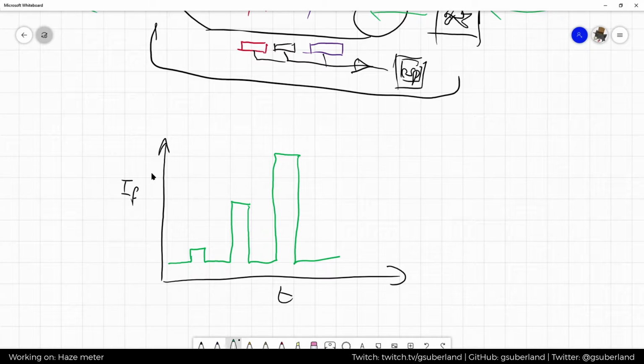So you first pulse a tiny bit of forward current, and then you take a measurement, and then you pulse a tiny bit of current again, a bit more current, and you measure again. And what you're basically doing is you're increasing the light intensity level for each one. And that way, when you measure the light level with the receiver, you actually get a better range of measurement because your light levels are changing.